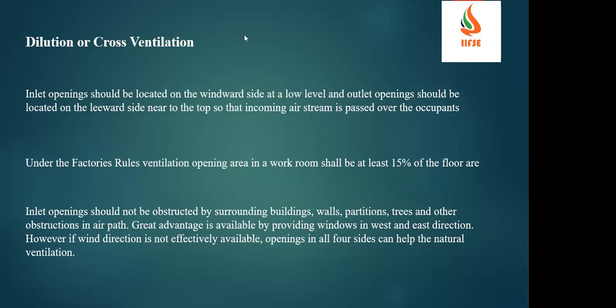As I'm explaining, for example, if your work area is about 100 SFT, then 15 SFT you should keep as openings for ventilation purposes. The 15 SFT may be in the form of windows, doors, or a secondary set of windows. That is one of the requirements.